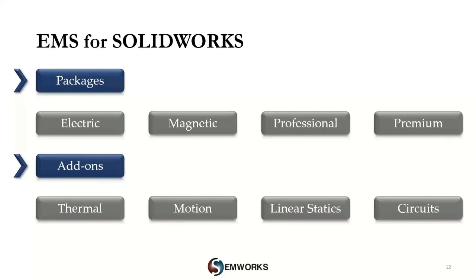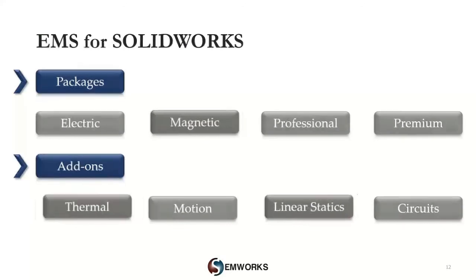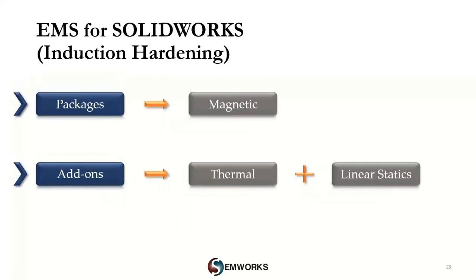EMS software is available in 4 package options, namely electric, magnetic, professional, and premium. To get more information on the software packaging and pricing, you can connect with me after this webinar. To simulate an induction hardening problem using EMS software, magnetic package with thermal and linear statics add-ons should be used.